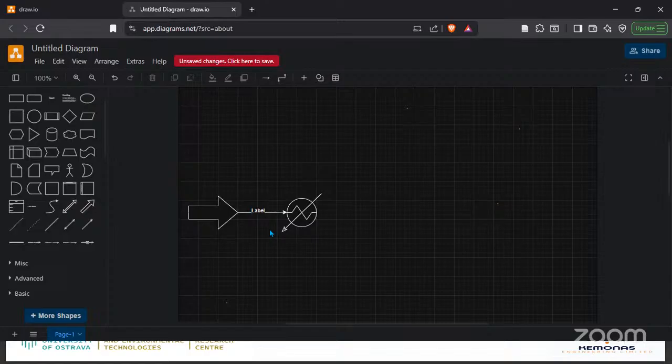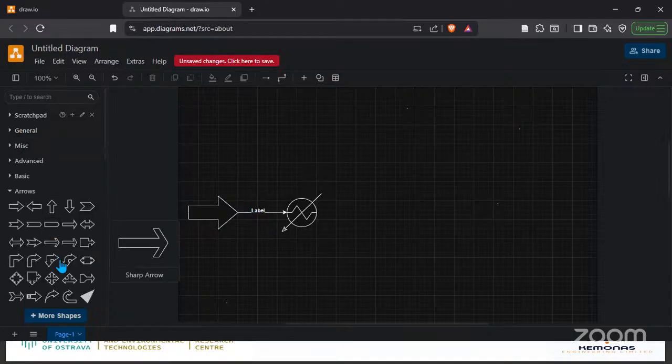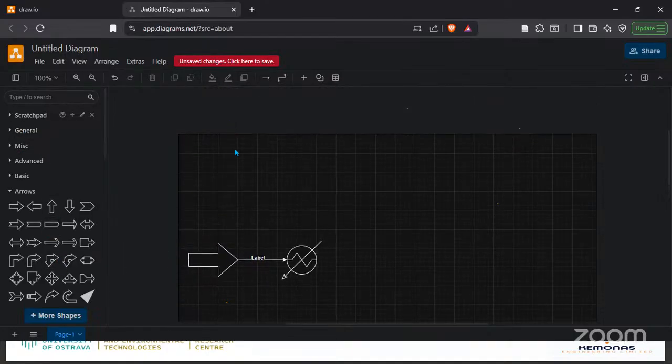So this is our feed. This is the battery limit, of course, and we need to include our test. Remember to leave space up here, and the reason you have to leave space up here is because above every equipment, you have to specify the equipment code or equipment name, and also the specifications of the equipment and everything.